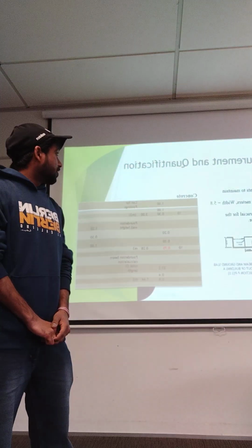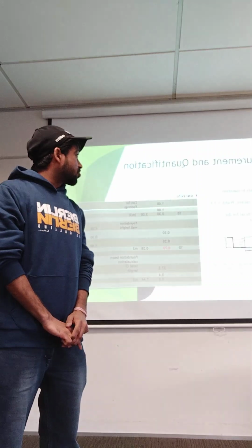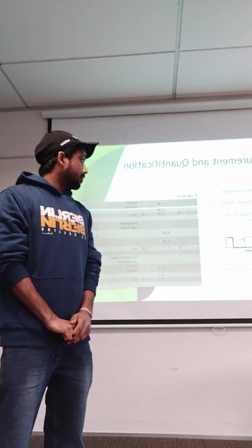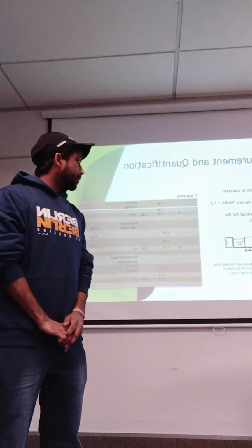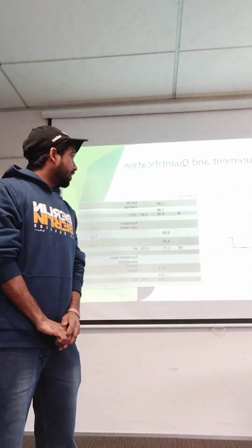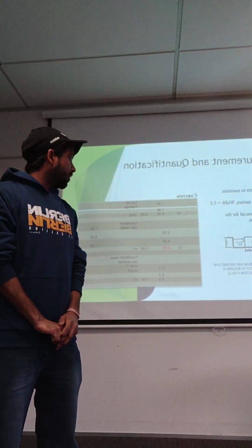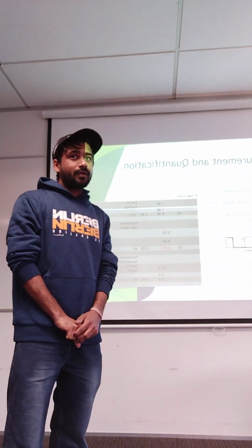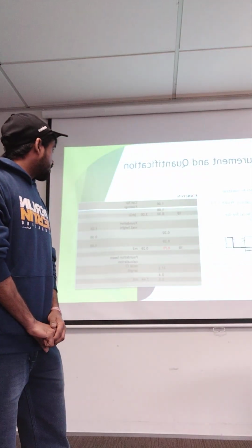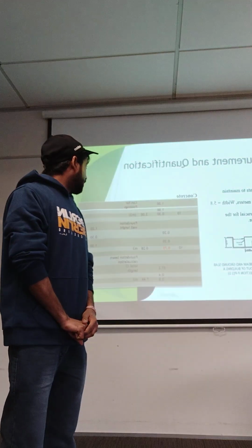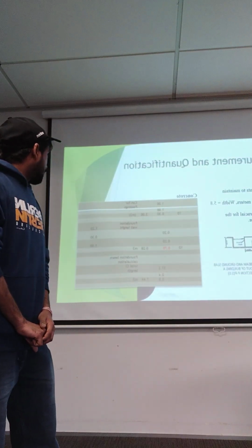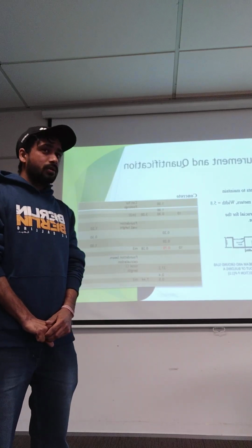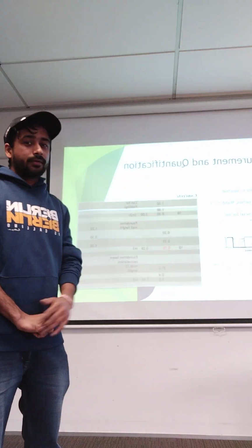Next is measurement of concrete work, which is essential to maintain structural integrity and is a very important sector in our foundation. Example of the dimensions: length 11.8 meter and width 5.8 meter. Ensuring accurate measurement is crucial for the strength and durability of our structure. These are the concrete calculations, with how to calculate the concrete for footing and foundation, height, foundation beam calculation, and total calculation of length according to the drawing.